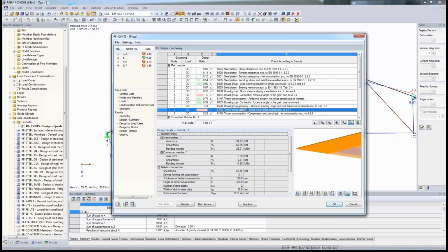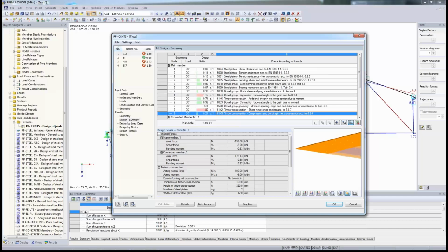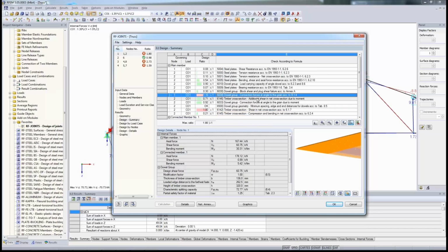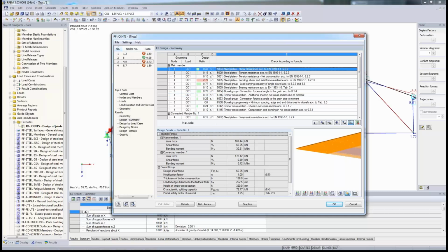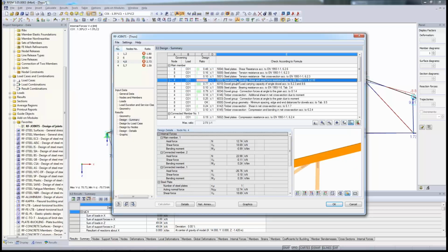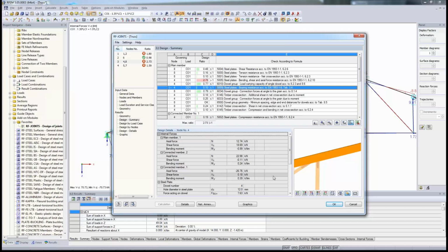Just have a short look. I have a timber overloading in this specific area here. Yeah, that was already a pretty close problem before. This tearing apart of the upper chord, and so here I have an overloading of the steel plate. Okay, that can be maybe improved by using 2 steel plates. But what I was up to show you was that you have completely different forces right now due to the stiffness. Okay, from my side, this is all, and I'm going to give the mic back to Gerland.